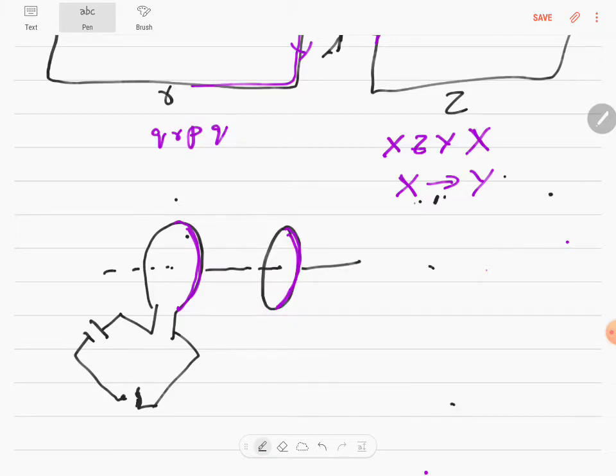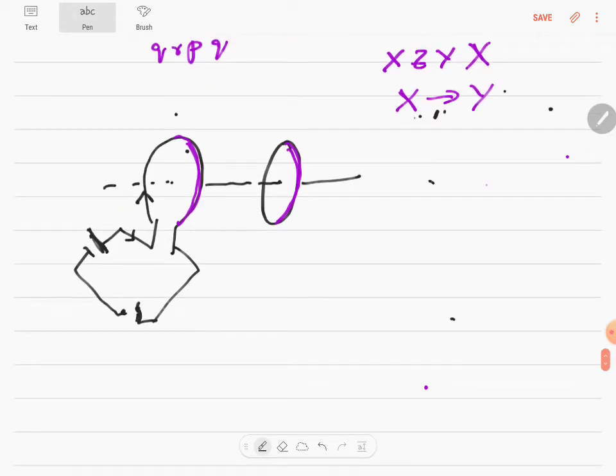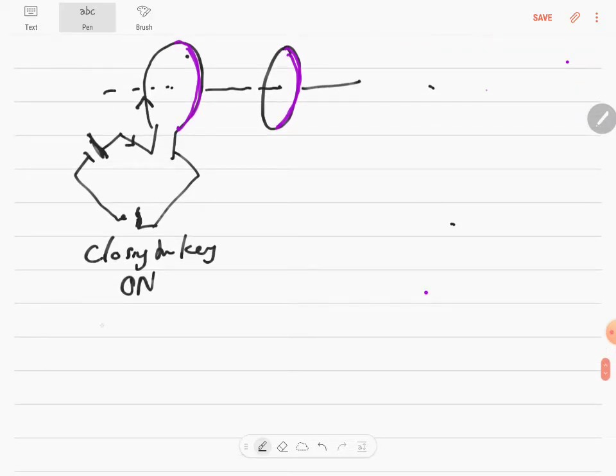So then therefore can you see the current is going to go like this, and the current is going to go like this in this coil. The question is about the key just closed. So we are closing the key. What is the meaning? We are switching on. Just the moment when you are switching on, the current rises from 0 to 5 amps, say for example. That's when there is a change in the current, di. Only when there is a change in the current, the magnetic field will change.